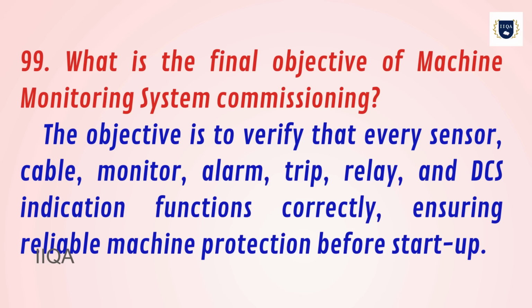99. What is the final objective of machine monitoring system commissioning? The objective is to verify that every sensor, cable, monitor, alarm, trip, relay, and DCS indication functions correctly, ensuring reliable machine protection before startup.